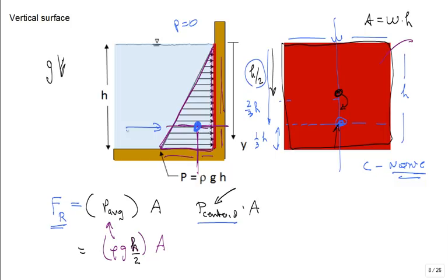But I don't want to apply my resultant force. No, that's where you apply it. It goes through that line of action, but you don't want to calculate the resultant force that way. You want to go to the physical, I can touch it area and get the centroid of that area, get the pressure at the centroid multiplied by the area. That's right, that's the average pressure.